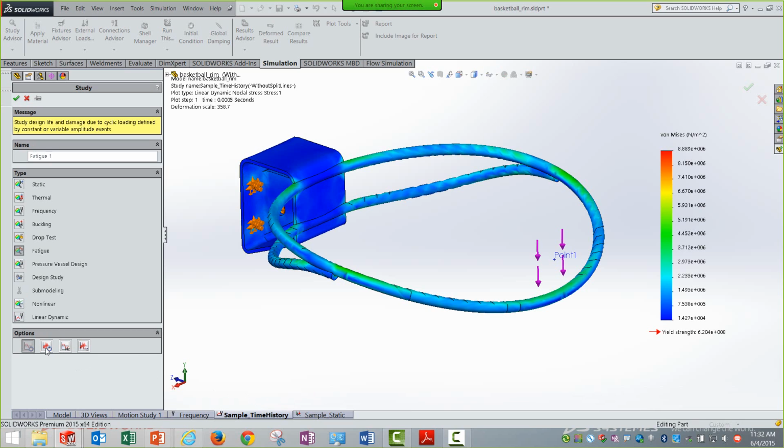Finally, in terms of fatigue, we have done this in Simulation Professional, so I'm not covering it in detail. When you select the fatigue simulation, in the past in Simulation Professional we had only one or two options, that was constant amplitude and variable amplitude. Once you have Simulation Premium, you get these options of harmonic fatigue, so obviously you need to do a harmonic analysis. Those loads can be taken for fatigue analysis.